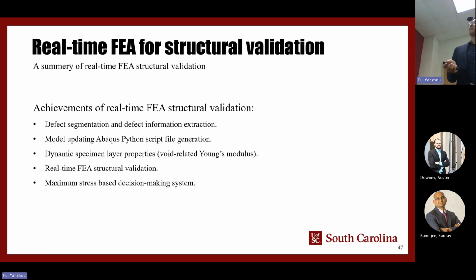So here is a summary of the real-time FE structural validation. We achieve the defect segmentation and defect information extraction, and we use this information to update the defect in the Python script. And we also propose the dynamic specimen layer property, which is the void-related Young's modulus. We also achieve the real-time FE structural validation, and the decision making based on the maximum stress.